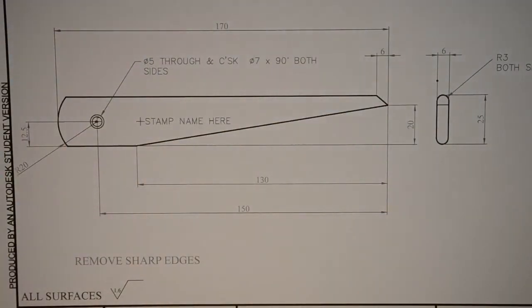We've got some common dimensions that you saw in that hideous sketch. It's 170 long. We've got that 130. But look, we now know how it's laid out. We know how it's measured. We know that this dimension here, this 150 for this length, is taken from the centre because it shows it on the drawing. So these are parts of the standard that go into making drawings understandable by everybody. That's why it's so important. We get an understanding of what these things mean.